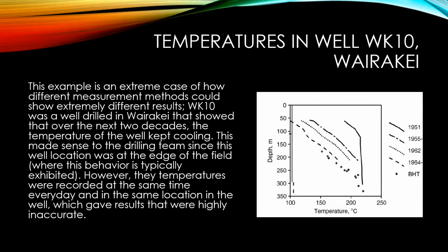However, temperatures were recorded at the same time every day and in the same location in the well, which gave results that were highly inaccurate. So every time they recorded, it was 12 hours after the well had been shut in and heating up, and they always went to the bottom hole. If the drilling team and the engineers had explored more different tests, then we would have had much more accurate results.